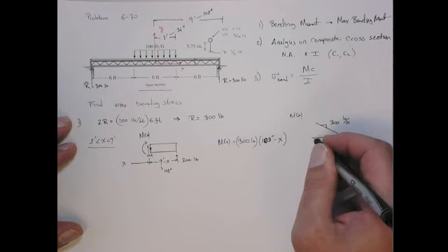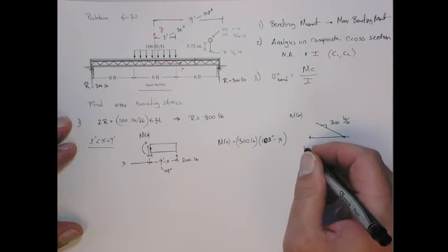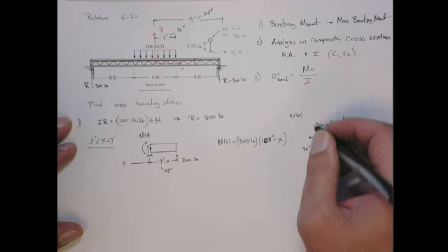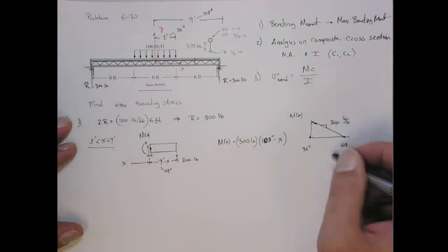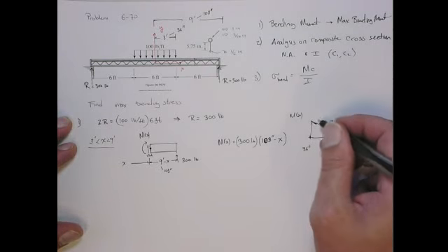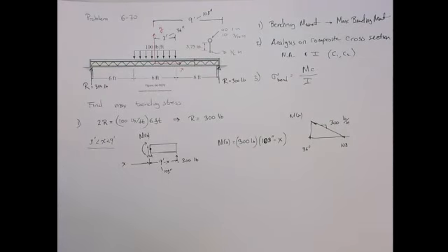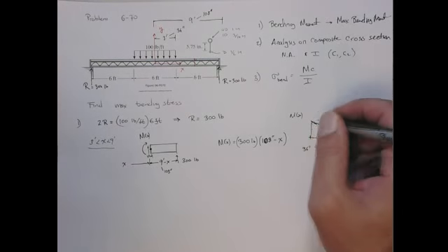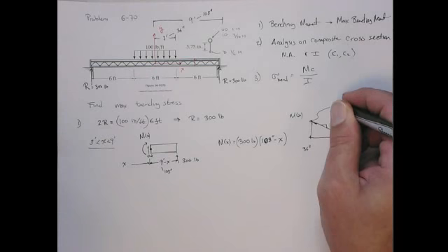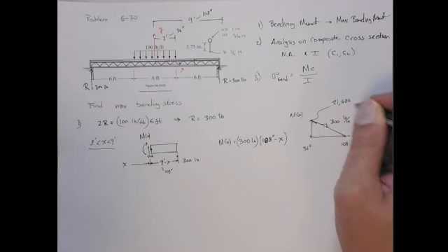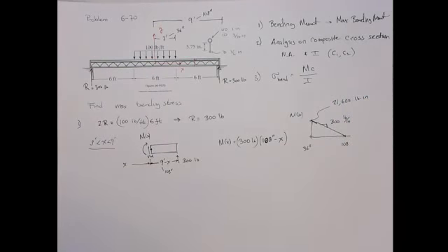I guess we should get it at 36 inches. That's the point where we switch over to having the effect of the distributed load. And if we do that, the moment there is going to be 108 minus 36, oops, I keep saying 30, 36, times 300. So at this point here, the bending moment is 21.6 kip inches, all right?